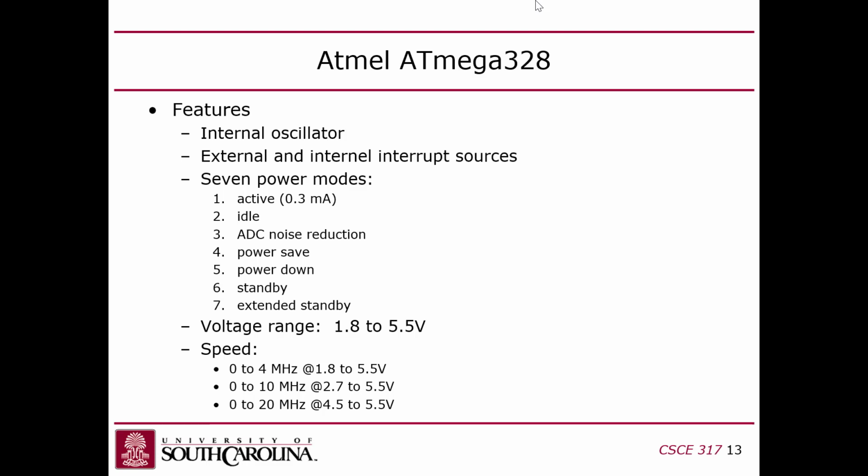So we're running at 16 megahertz, and we're running at 5 volts, right? This does introduce some complications because some of the external peripherals that we want to use run at 3.3 volts, so we'll have to build in some voltage level shifters for them to talk to one another.